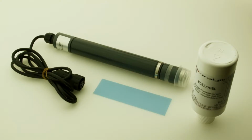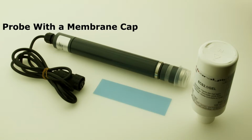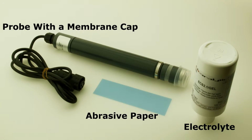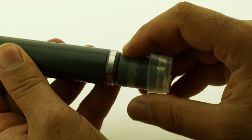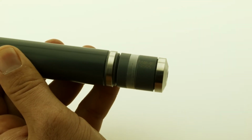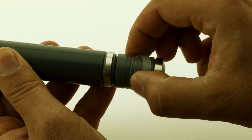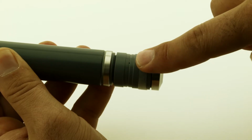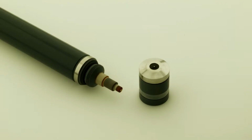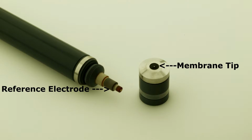The sensor kit includes a probe with a membrane cap, a 1-year supply of electrolyte, and a single piece of blue abrasive paper. Certain precautionary measures must be taken. Before a membrane cap is ever removed, it is critical to slide the elastic seal away from the tiny vent hole. Failure to do so can result in permanent damage to the membrane. Also, do not touch the membrane surface, which is located on the tip of the cap, or the gray-colored reference electrode.